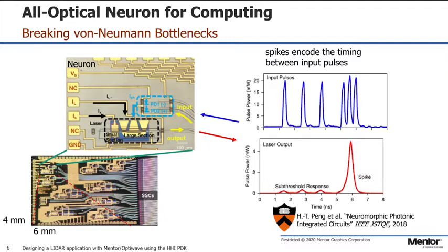The DFB laser itself is biased just below threshold, so you can easily kick it above threshold if you just supply enough current. However, it is biased such that a short spike of electrical current that is generated by just one optical pulse is not enough. But if you have several pulses in rapid succession, then they would basically be integrated by the laser, and the laser goes above threshold and starts lasing for a short amount of time.